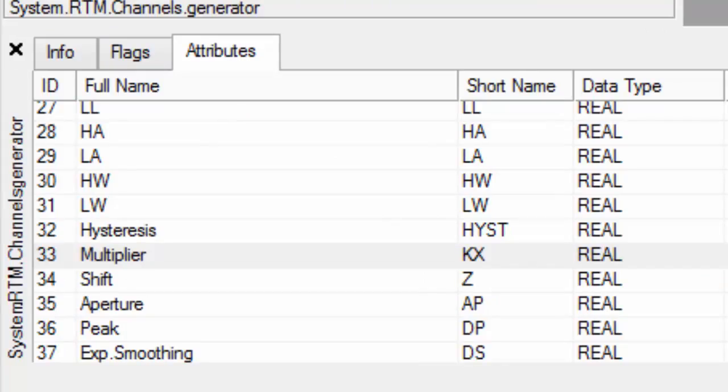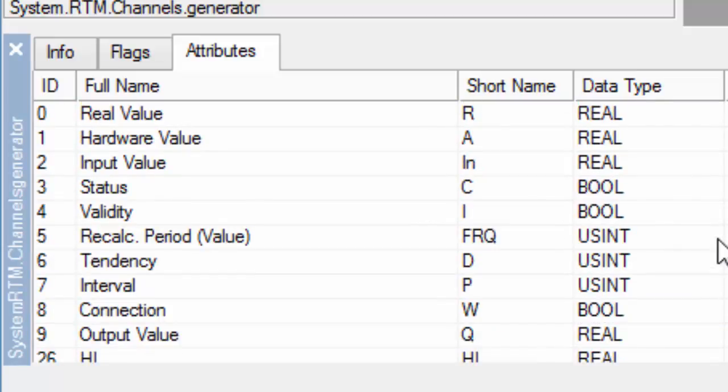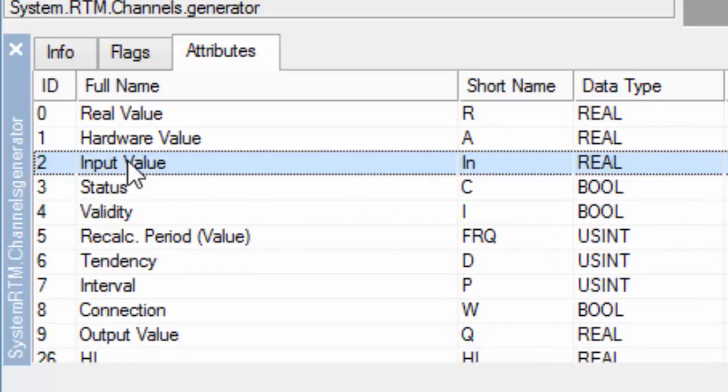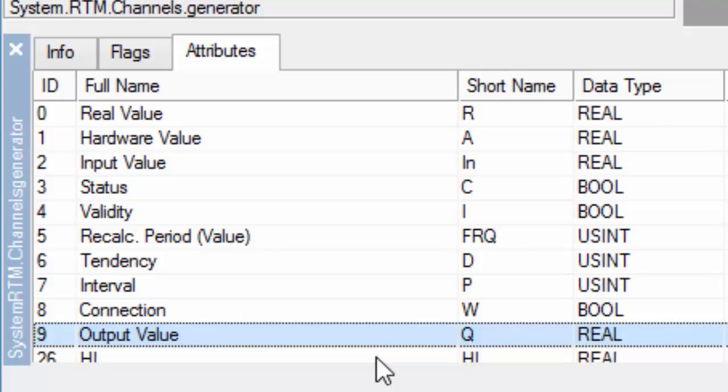The most important feature of SCADA Trace Mode is the ability to link the not calculated attribute input value for the input type channel to any attribute of any channel, local or remote, or a hardware-software data source. Accordingly, for the channel type output, the calculated attribute output value can link with any not calculated attributes of any channel or hardware-software data receiver. The channel has only one link at any given time.